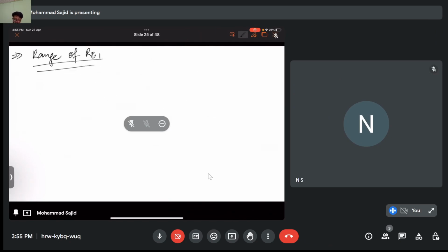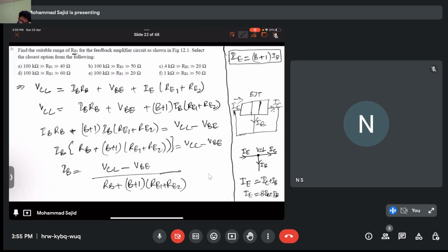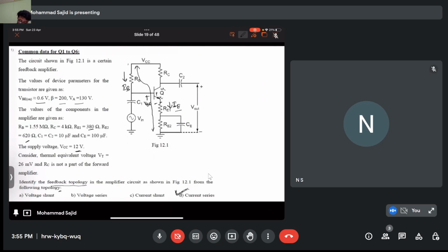Now for the transistor, in the feedback, we have a few conditions, right? First, you gave the right answer when you said that it is current series. So your feedback element is RE1, right? And if it is current series, then your feedback voltage is Vf and your current is IE1.